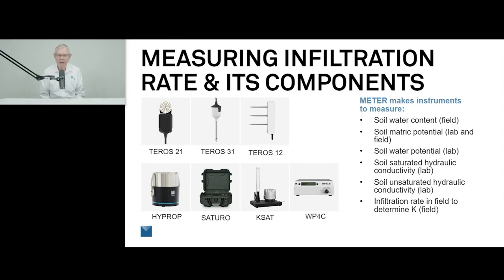The HYPROP measures unsaturated hydraulic conductivity and moisture retention of cores that we bring to the laboratory. The Saturo measures infiltration rate in the field, and it determines the field saturated hydraulic conductivity. All of these measurements relate to infiltration, but today we want to focus on the ones that actually measure hydraulic conductivity.